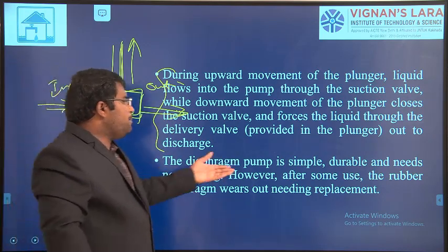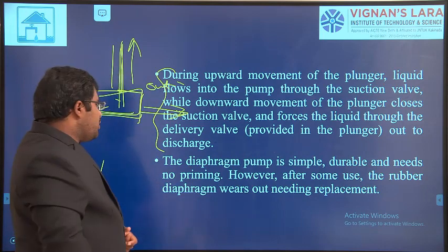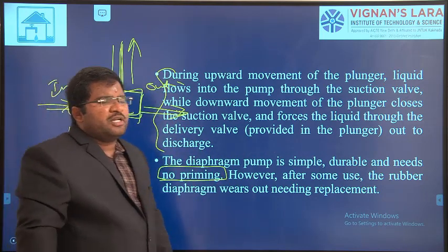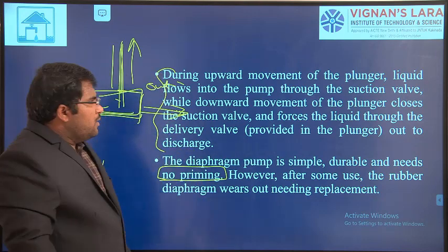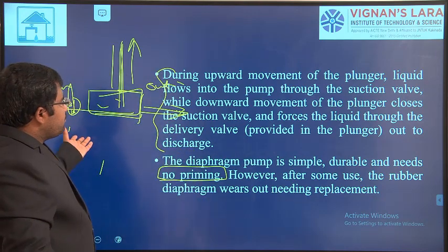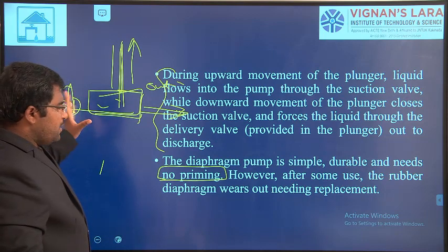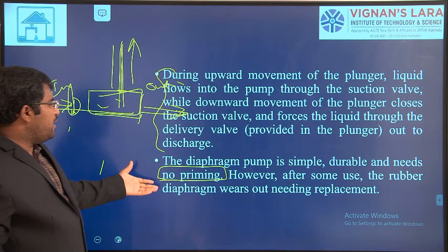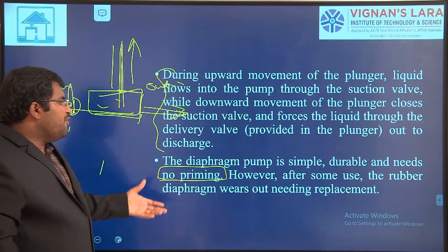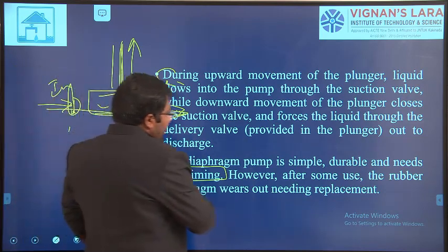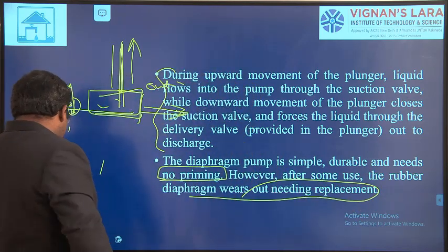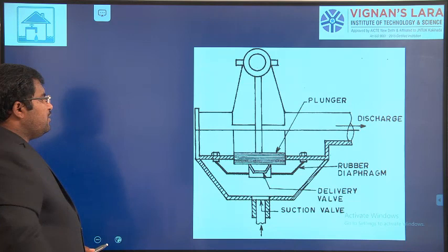Next, the diaphragm pump is simple, durable, and needs no priming. Normally, for a reciprocating pump or centrifugal pumps we need priming, but here we don't need any priming. However, after some use the rubber diaphragm will tear and we need to replace it.